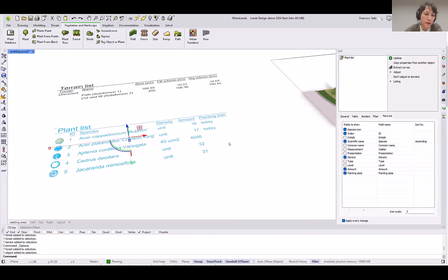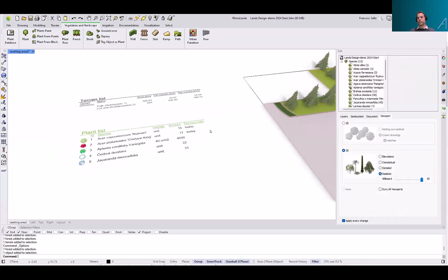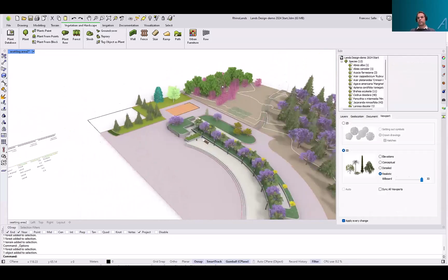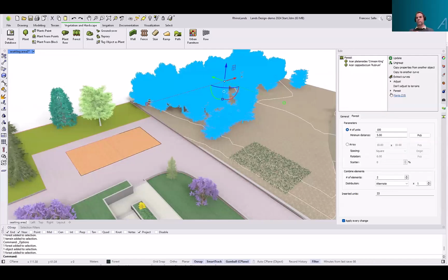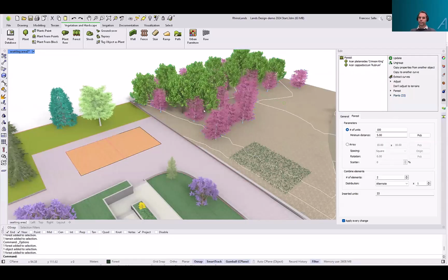Oh yeah, that's actually pretty useful. Does it also work if you export it to an IFC or use the Rhino inside Revit? Does this also export to Revit, so that you have these parameters in a schedule in Revit? Correct. The values assigned to objects are exported as IFC properties. So if we export that model to IFC, all these plants will have this information stored in the geometry. So you will be able to read it in Revit, for example.